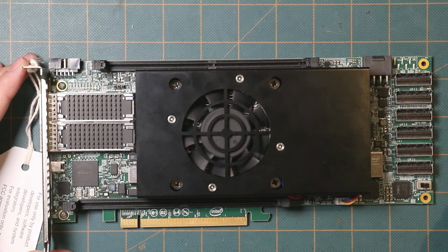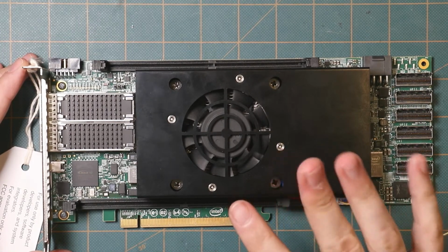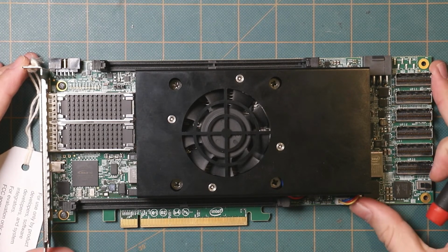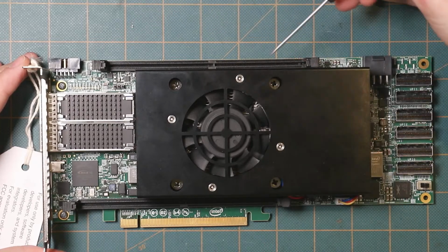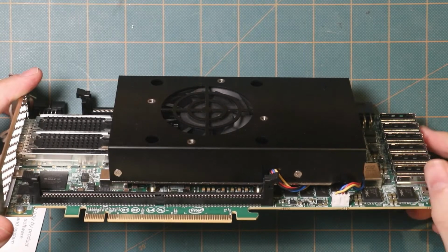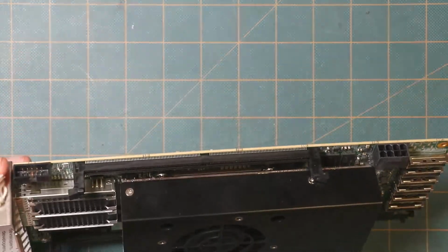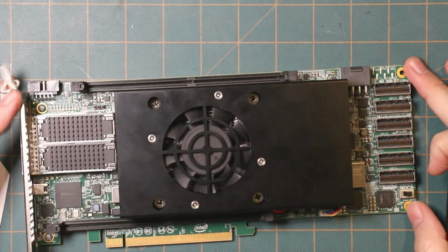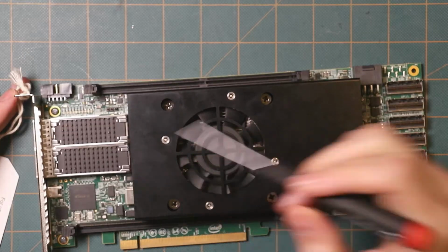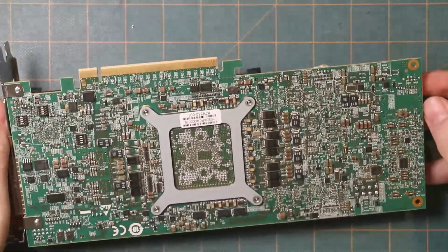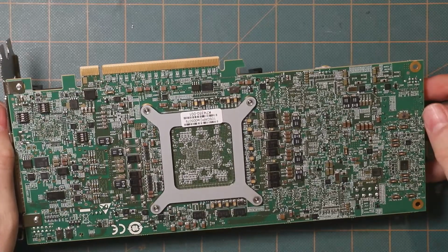And this FPGA, I think, has 4 of the P tiles on it. So one of them is hooked up here, and then one is hooked up to each pair of these guys over here. Then there's 2 DDR memory slots here, and then we have 1 bank of DDR here. And there should be another bank of DDR over here. And then obviously there's the pair of QSFP modules here. And that, I think, just about rounds it out in terms of actual peripherals.